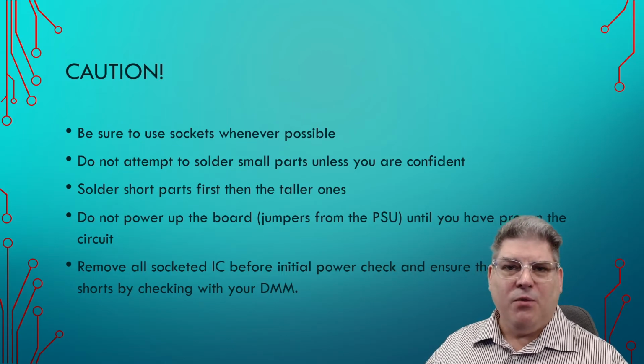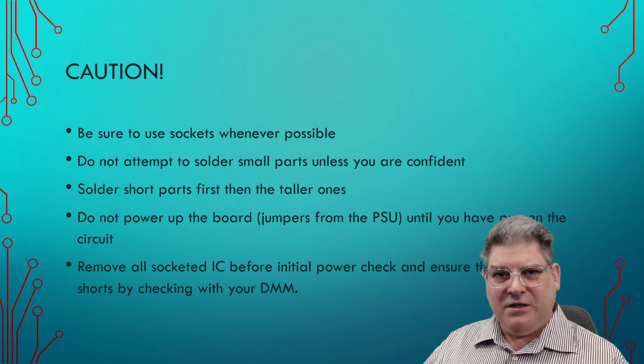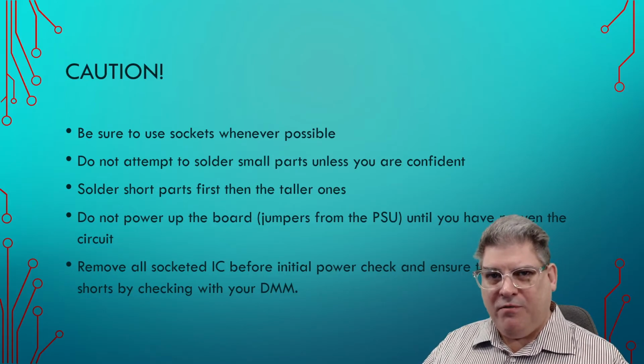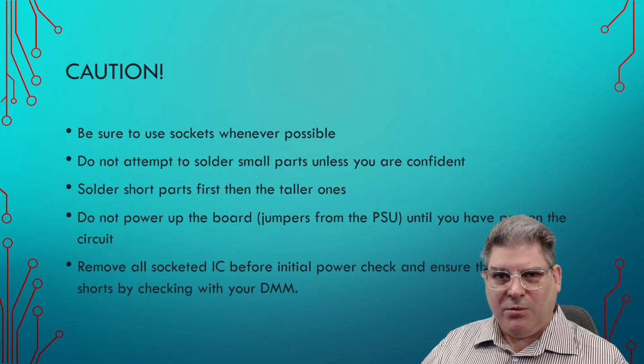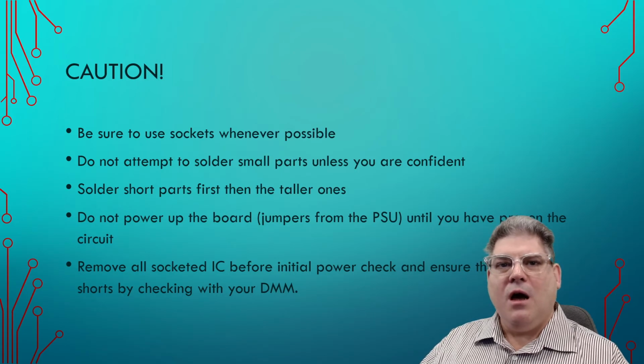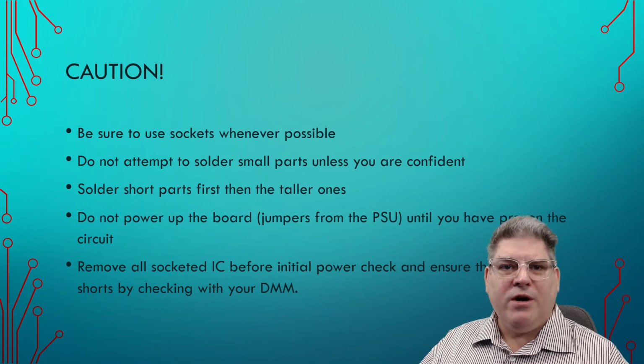And so one of the things that we can do with our circuit board is remove those jumpers, check it, make sure that your power supply is good, and then power it up. If you don't have 3.3 volts, stop and troubleshoot the power supply. Once your power supply is good and you don't have a short on the microprocessor side, then you can put the jumpers in and try to power it up. Should your power supply then be good, we can try to program it.